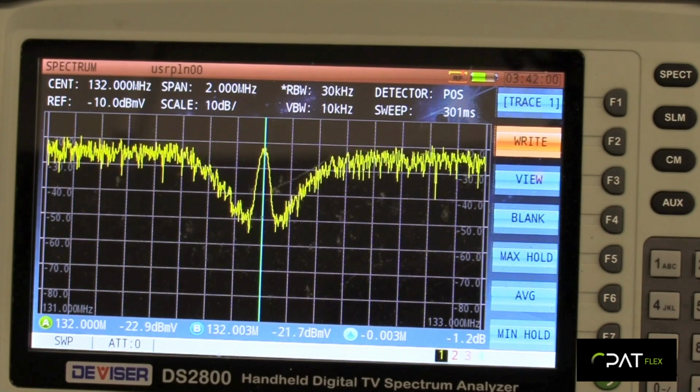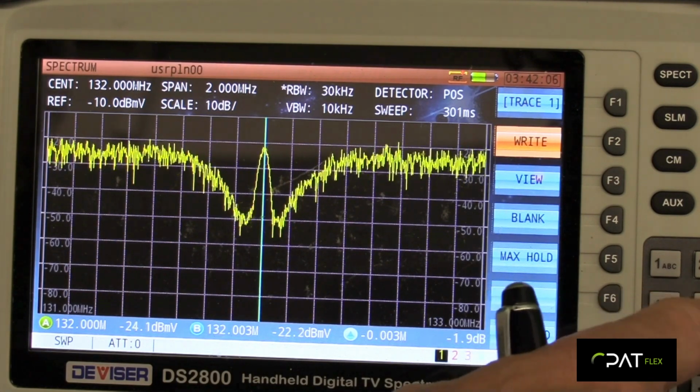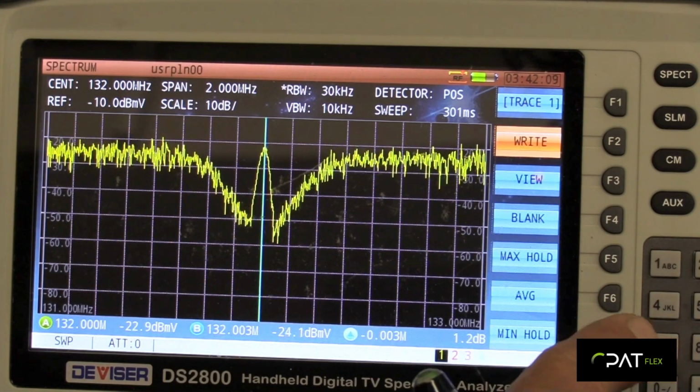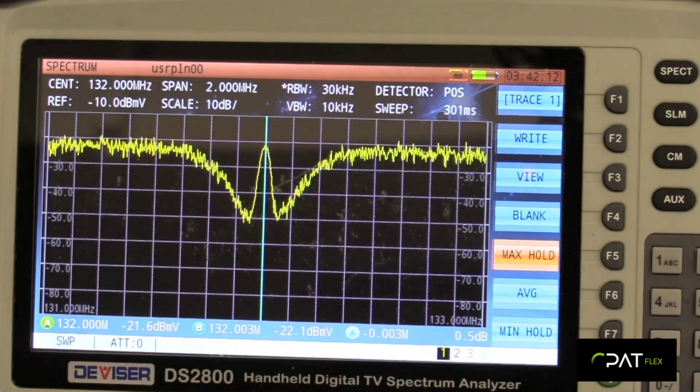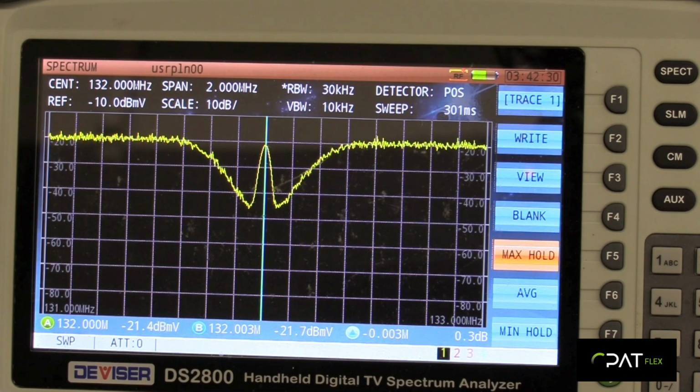Inject the DSG1 carrier and use a marker on the center frequency to make a measurement, remembering to put the analyzer in peak hold in order to obtain the maximum peak of the DSG1 carrier. If necessary, fine-tune the attenuation to obtain the nominal delta between QAM and DSG1 carrier. The objective would be to set the DSG1 signal as high as possible while maintaining acceptable MER degradation.